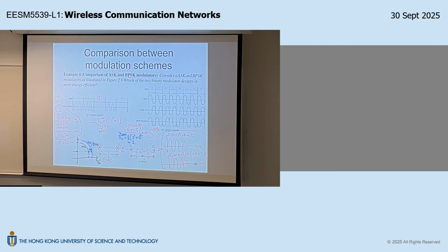So now you have pulled these 2 points away, right? So that means you're spending extra energy on these 2 points, on these 2 symbols. So in order to satisfy the total average energy constraint, that means these 2 points must be put closer, right? Otherwise, you will violate the constraint. The energy constraint is your budget, right? Think about that as money. You spend your money to pull these 2 guys away, right?